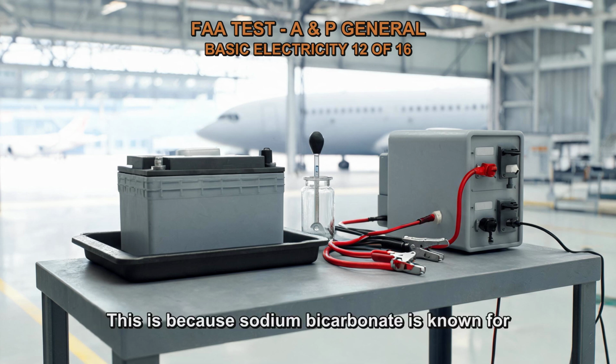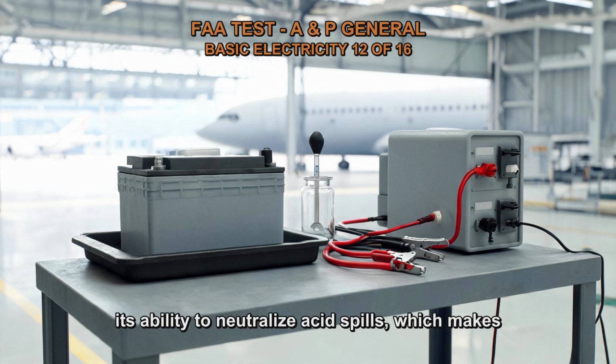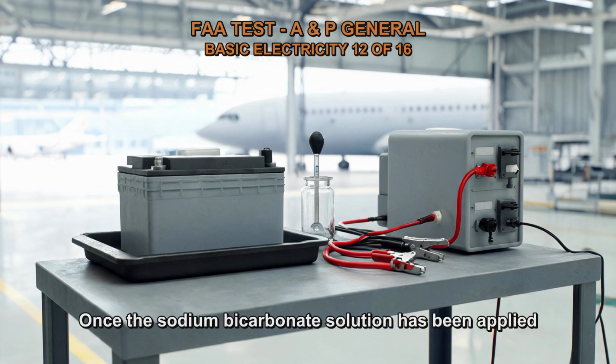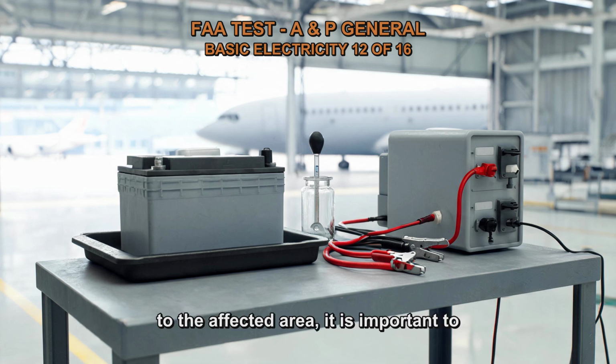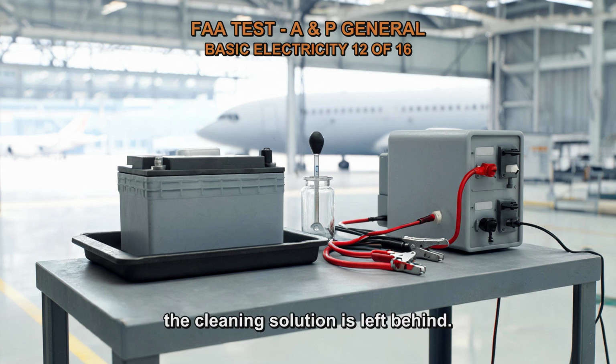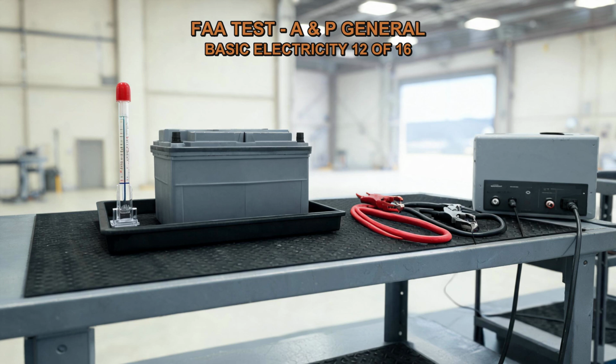This is because sodium bicarbonate is known for its ability to neutralize acid spills, which makes it a suitable solution to use for cleaning up electrolyte spills from lead-acid batteries. Once the sodium bicarbonate solution has been applied to the affected area, it is important to rinse the area thoroughly with clean water to ensure that no residue of the electrolyte or the cleaning solution is left behind.